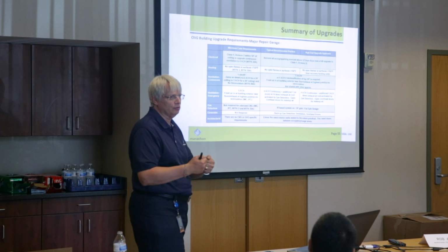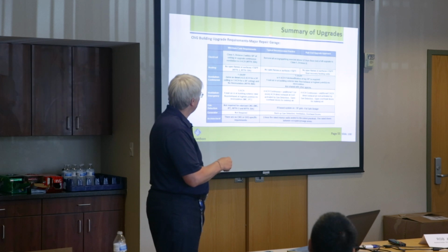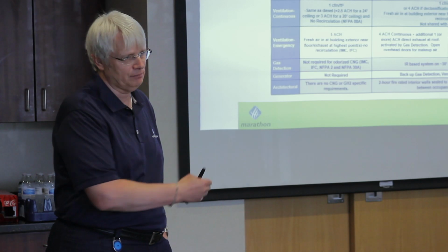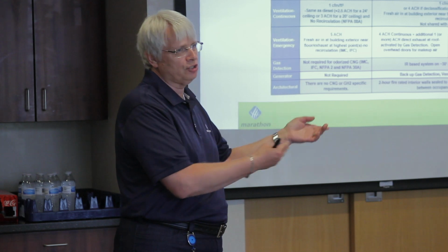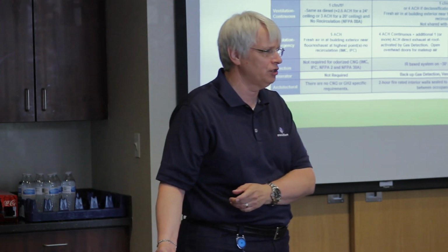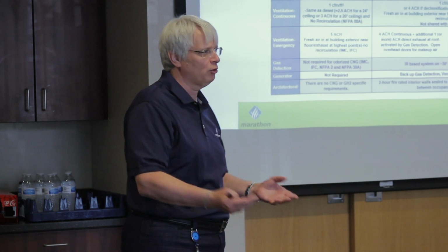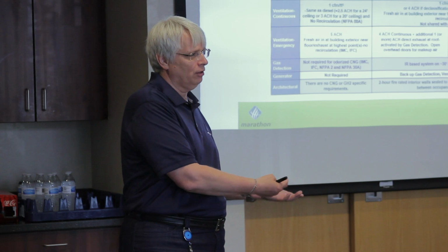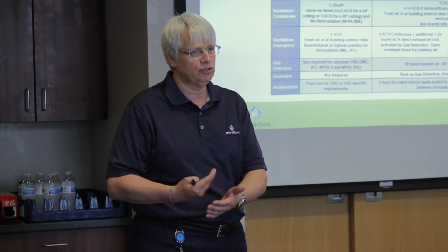But as I've also said, many people do this throughout their facility. Because logically, if you could have a gas release in the maintenance area, you could just as easily have a gas release in the storage area. And in fact, it might be more likely to happen in the storage area because most people, when they pull buses in for maintenance, they don't fuel them. They pull them in half full. Whereas when you pull them into a storage area in a bus fleet, they are always full.